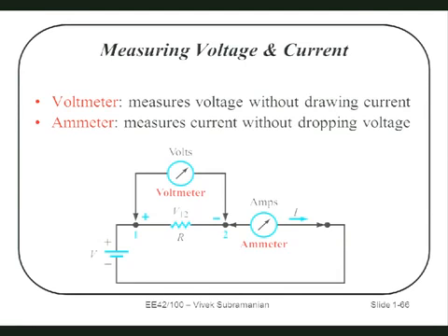You want to measure the flow through the pipe, you would want to put a flow meter on the pipe so you see how much flow goes through it. It's the same sort of deal. That's what an ammeter does. Now, for that situation, what would you want the characteristic of the ammeter to be? Would you want it to have a really, really high resistance or something different? Very, very low resistance, ideally 0.